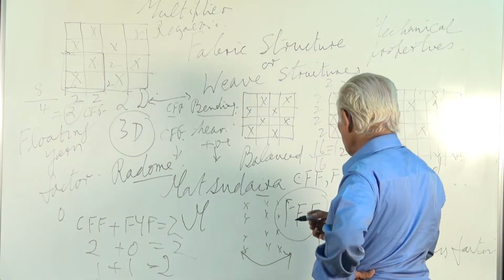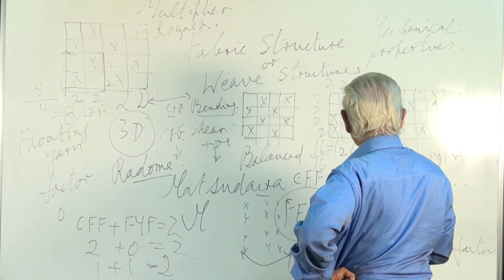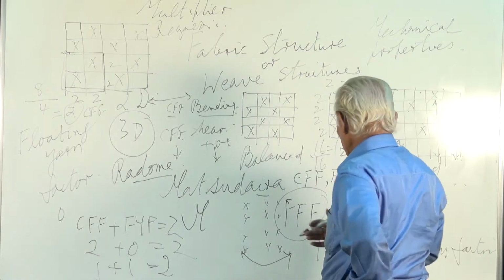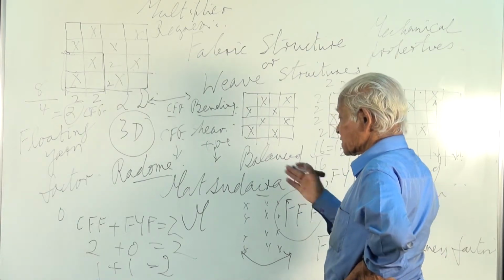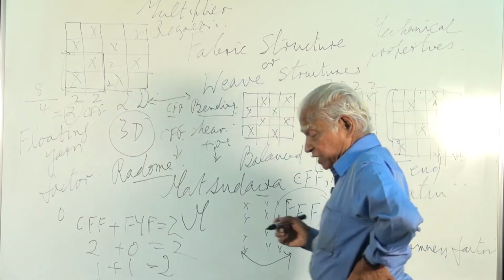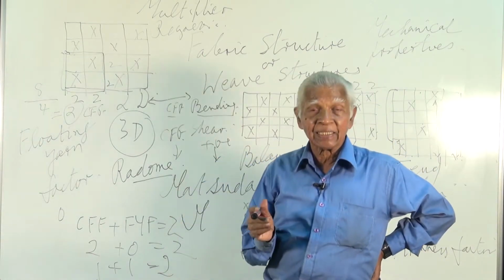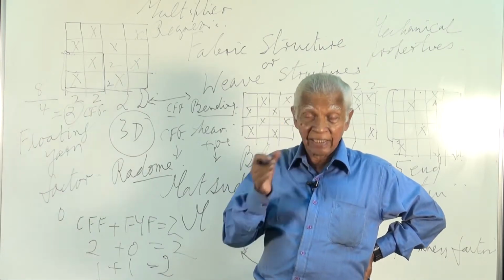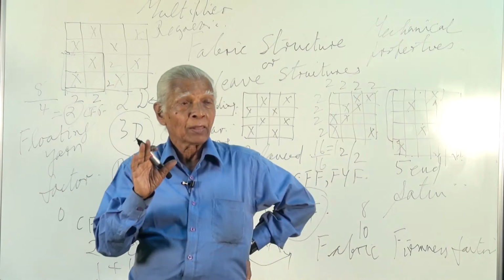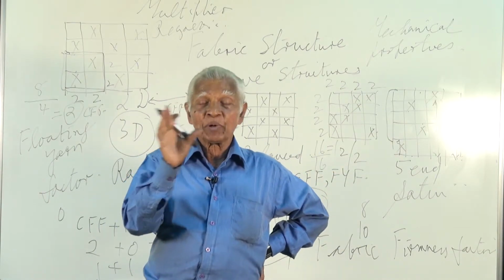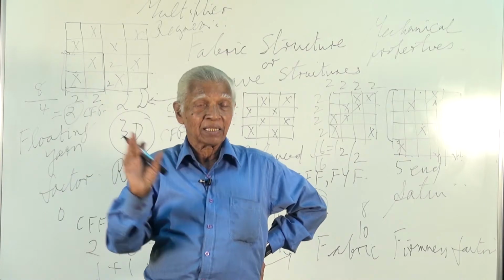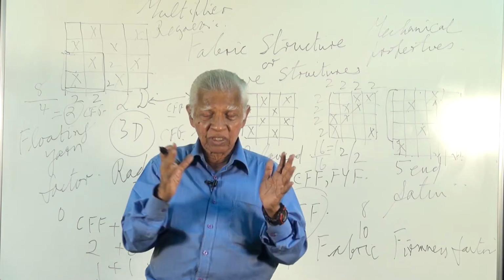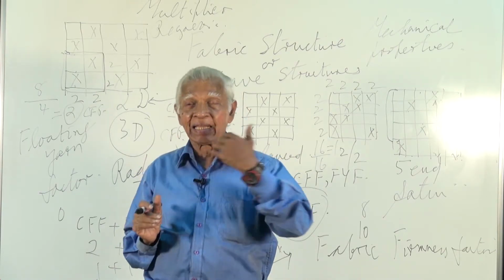the honeycomb fabrics, but a lot of work remains to be done with other structures in order to establish a relationship between the structure and the property. In fact, structure-property correlation has attracted the attention of so many workers. It has been done in the case of fibers. A fiber which has a higher orientation, even among the cottons, gives a higher strength. So there is a positive correlation between orientation and strength. Then crystallinity, the higher the crystallinity or the packing of the molecules inside the fiber, the greater the strength.